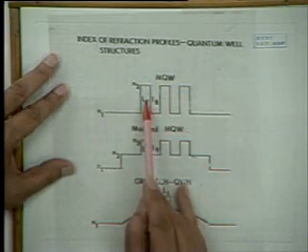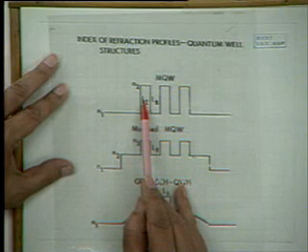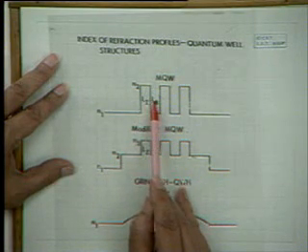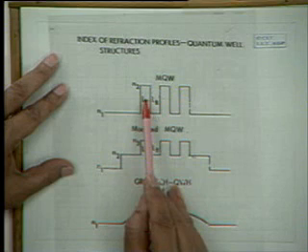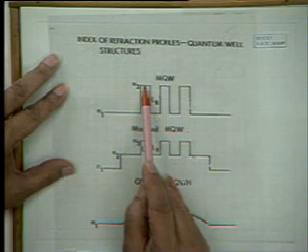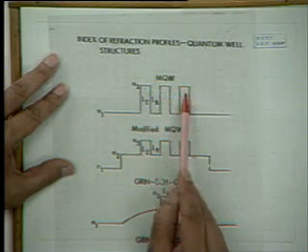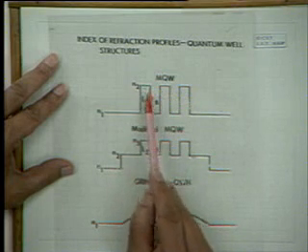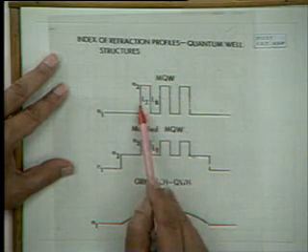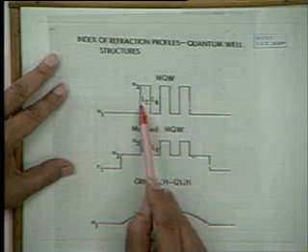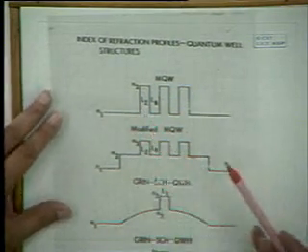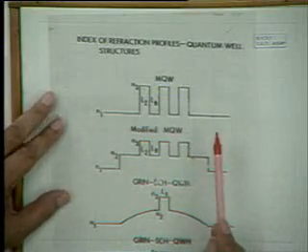These are the wells and these are the barriers, because the refractive index in the well is high. So there are 3 wells. Obviously there will be some confinement here, but because these Lz are very small, the optical confinement is going to be much less than in the case of a double heterojunction laser.